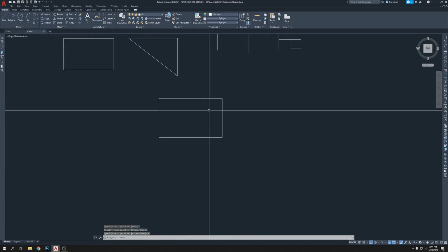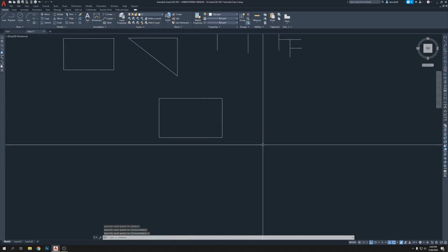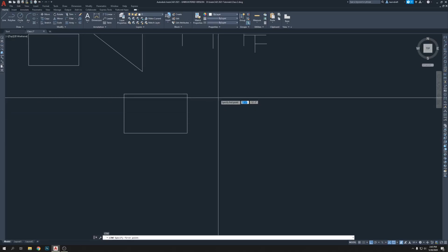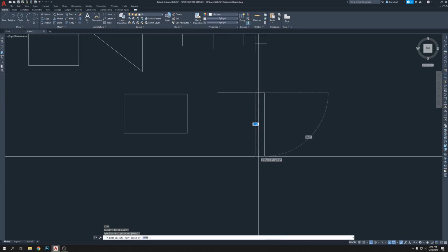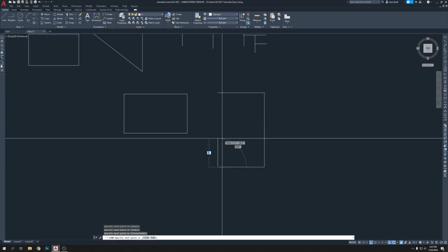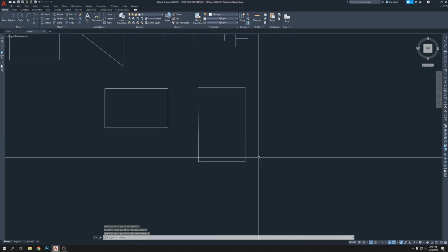So this is a rectangle. We are not doing it with dimension, we're gonna do it later, and there is a command for rectangle we can do later. And now this was a box. Again, L, enter, click, click, make it longer this way, click, and then C, enter. So another box.